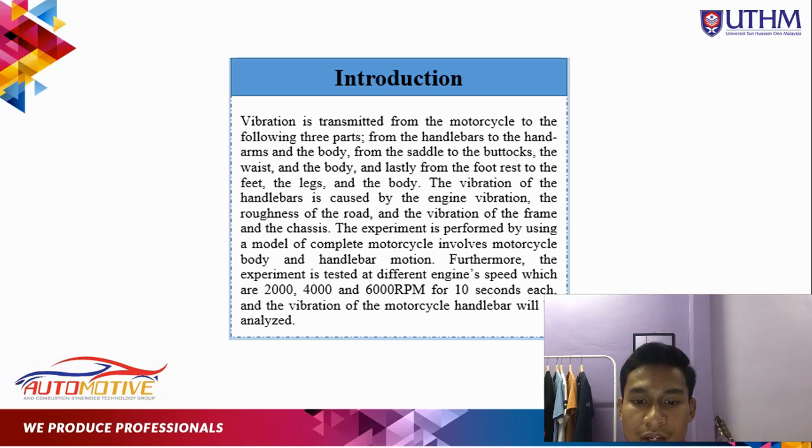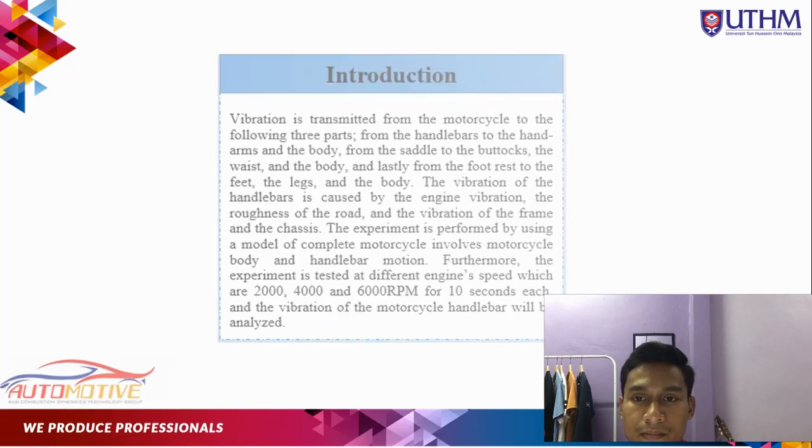The vibration of the handlebar is caused by the engine vibration, the roughness of the road, and the vibration of the frame and the chassis. But in this study, the engine vibration will be the main concern. This experiment is performed by using a model of a complete motorcycle involving motorcycle body and handlebar motion. Furthermore, this experiment is tested at different engine speeds, as mentioned before, which are 2000, 4000 and 6000 RPM for 10 seconds each, and the vibration of the motorcycle handlebar will be analyzed.